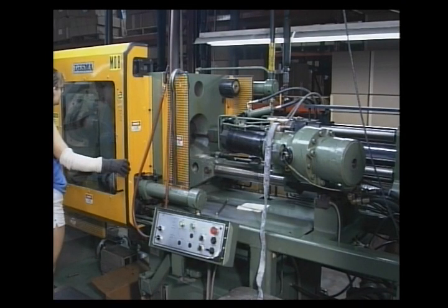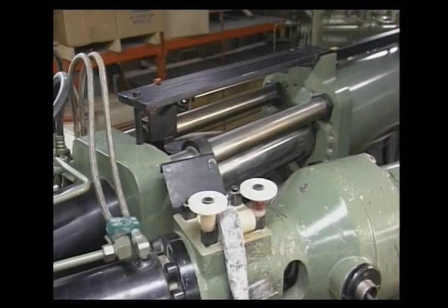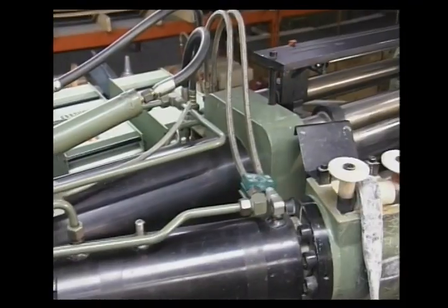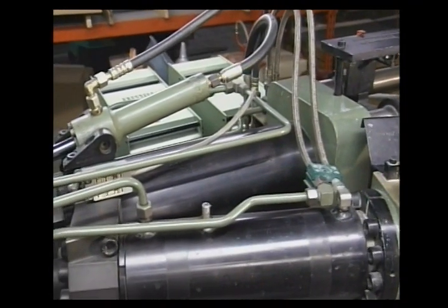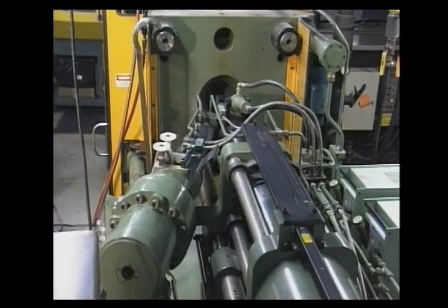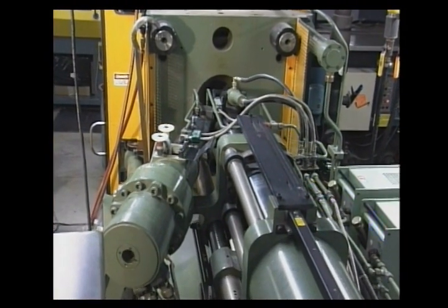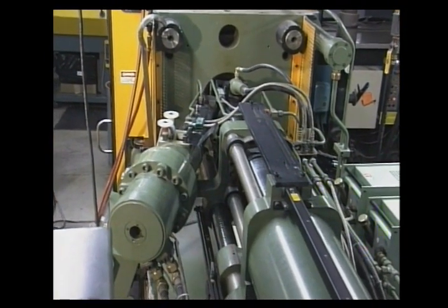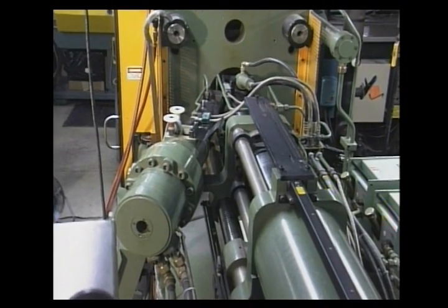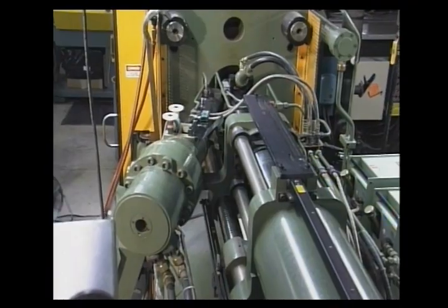The 2-stage screw-type machine has a screw which constantly forces melted resin into a second straight bore cylinder with its own plunger. When the correct amount of material has been transferred, the screw stops turning, and a valve closes, separating the cylinders. The plunger pulls back to decompress the material, which is then injected into the mold.